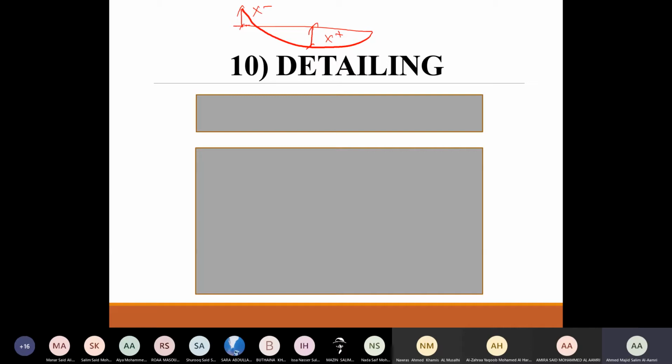It means that I have the reinforcement of x. There will be a reinforcement of x in this direction, which is for the bottom. And we said for the bottom we are going to continue it from the beginning till the end, if you remember. And there is a negative bending moment, which is representing a top reinforcement. So there will be another reinforcement here for x, only for the position of the negative. After that, we are going to place our y. So these are going to be our y bar reinforcement according to whatever we have calculated in the AS provided.